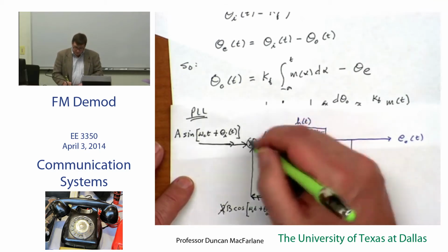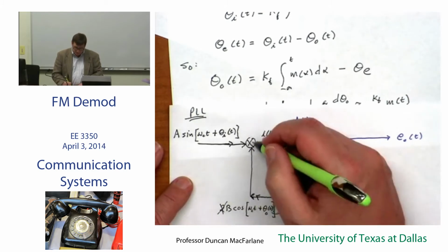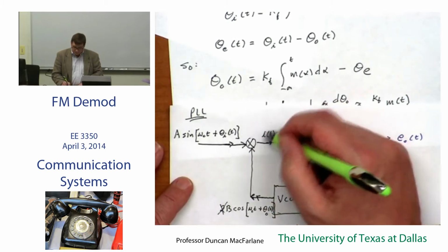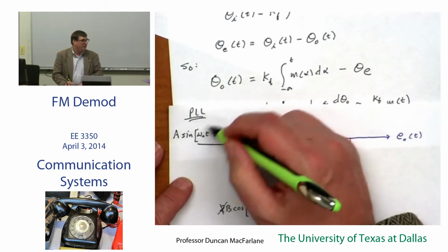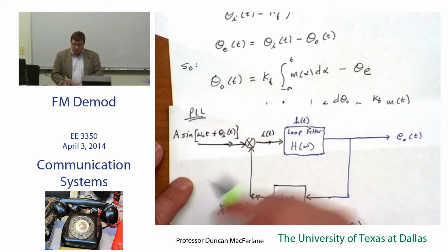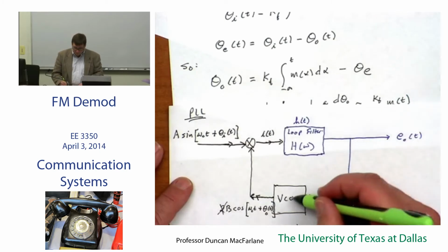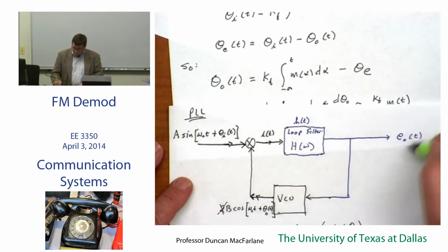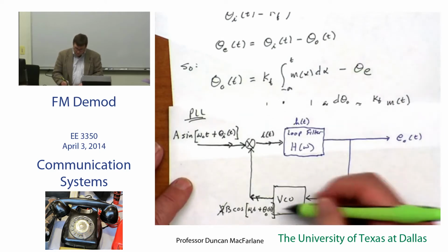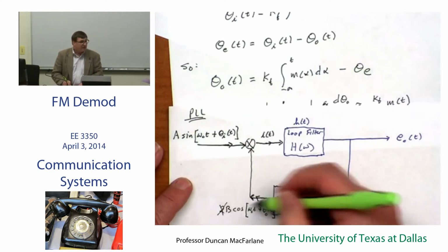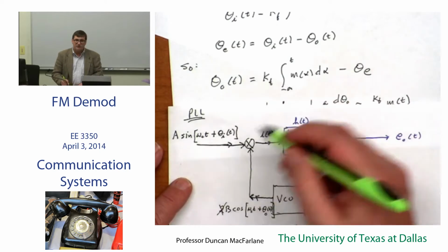And so I of t, this mixing and this regeneration here work brilliantly to give you an I of t that's robust, even if this guy is weak. And then the rest of it, I do a little bit of filtering and I feed back, and the E out of t, through the math that I just showed you, readjusts to keep getting this closer and closer into lock.